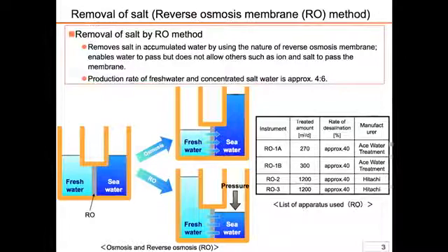Generally, fresh water is delivered to the seawater side to equalize the density of salt when we separate the seawater and fresh water with the RO membrane. The fresh water penetrates to the seawater side till the density of salt in the seawater side reaches a certain level. Meanwhile, it is the RO membrane's job to reverse the above function. To reverse the function, the mechanism is that of pressing the seawater side to transfer only fresh water to the left side, the freshwater side.